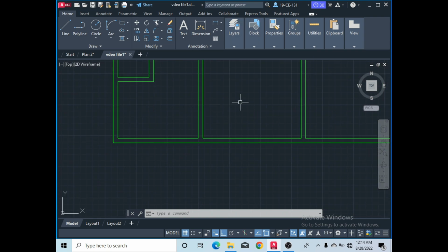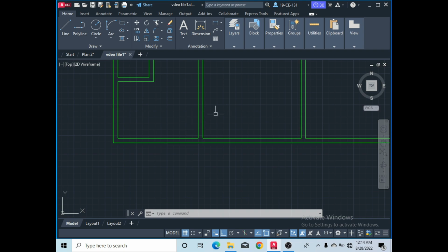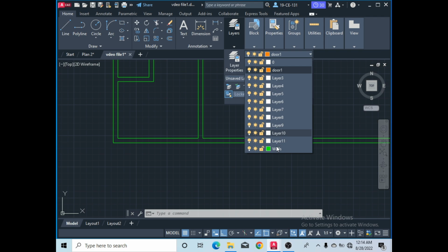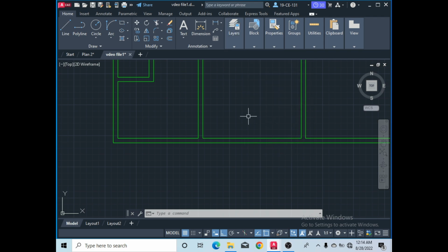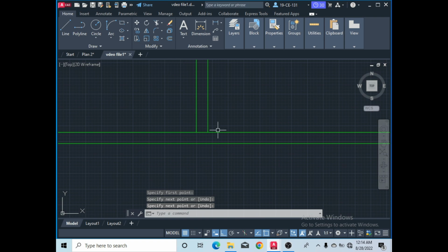But before starting to draw the doors, I would like to first complete this opening. So let's start from the opening and select the wall. Right now start from the line command and simply click here and draw a small line. You know that our doors are 3 inches away from this wall, so simply take the offset command and type 3 inches. So press enter.